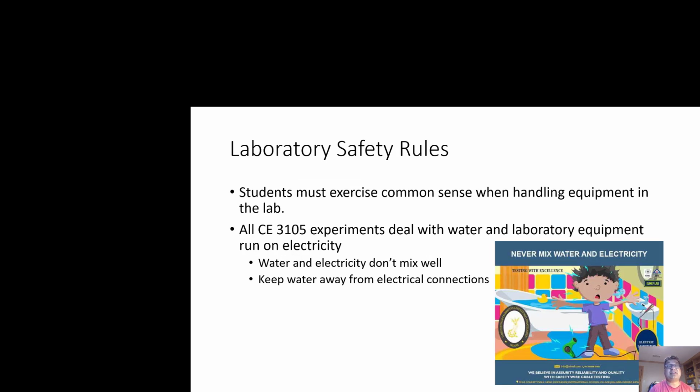In terms of our fluids lab, obviously we'll be dealing a lot with water. And of course, all our instruments run on electricity. So the biggest thing to keep in mind is that water and electricity don't mix well. So keep water away from the electric connections so that there is no short circuiting or electric shock to anybody. The key requirement there is to ensure that there is no water being spilled or getting close to the electric connections.